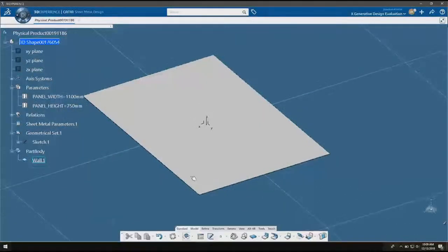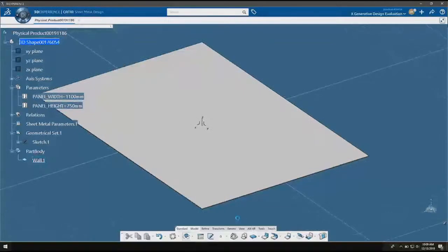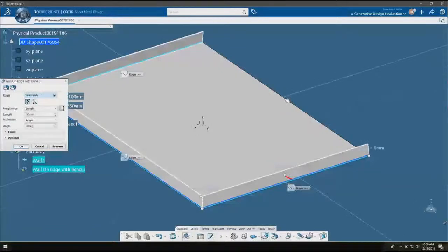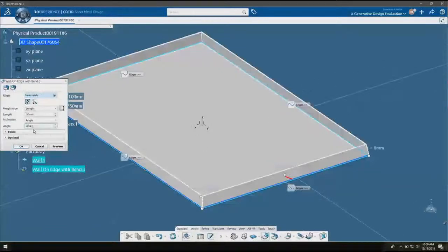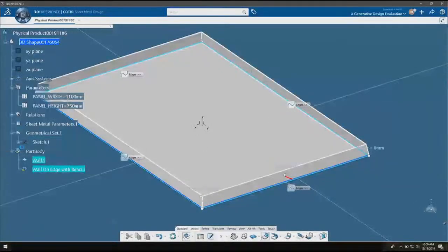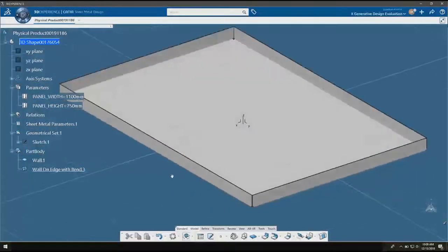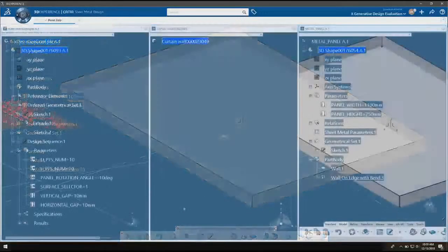And now I'm going to create a new part inside using the sheet metal design application. The sheet metal design application will allow me to make this panel, and it does the calculations for K factor for folding and everything like that. It does the notching based on the machining requirements. It includes an unfold view that I can project into a drawing for manufacturing.